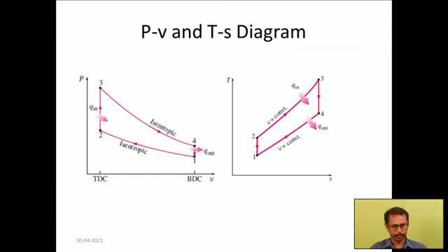During this process, the heat is rejected from the combustion chamber to the atmosphere by bringing a cold object to the cylinder head, so the heat will be removed. So this process is happening at constant volume. So this process is called the constant volume heat rejection process. So again the point 1 is reached. It is a thermodynamic cycle.